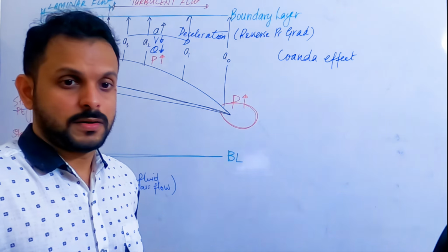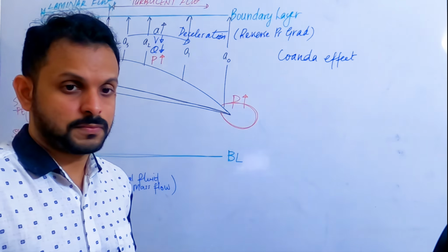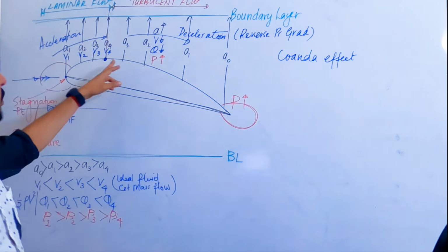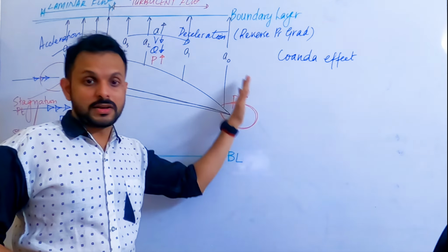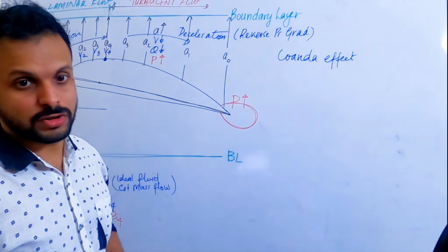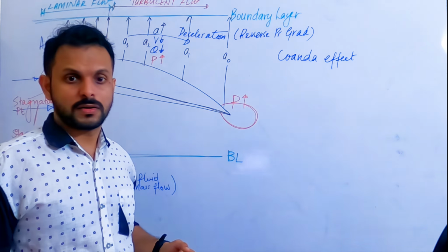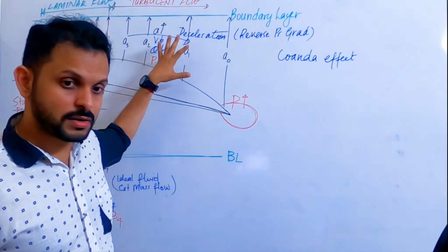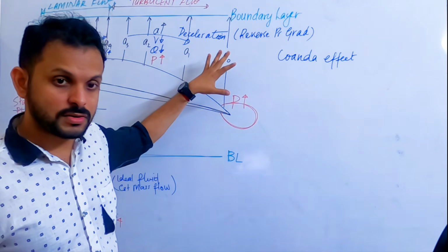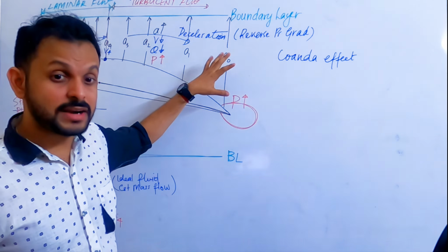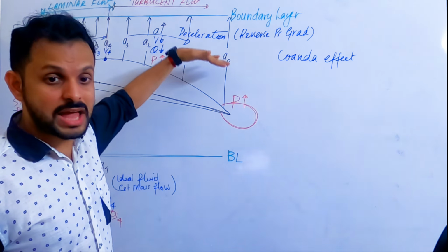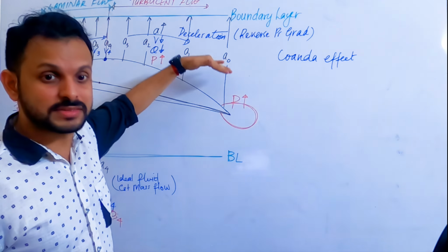But then how is the static pressure higher? Because at the front part of this, the static pressure is higher, no? That you just told. Yes, and static is lower here. The static is also increasing all the way to the trailing edge. How is it higher? What happens to the speed of the air molecules here? It is decreasing. So now the air molecules can actually be here for a longer time and impart a bombarding force of static pressure on the surface.